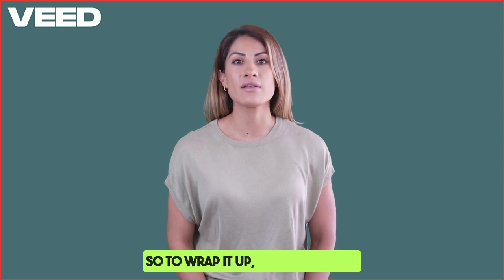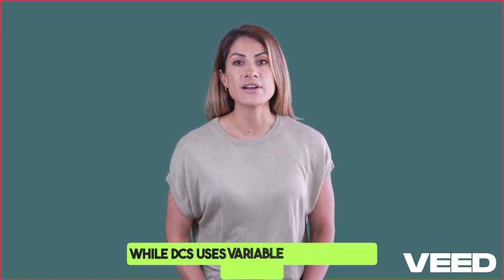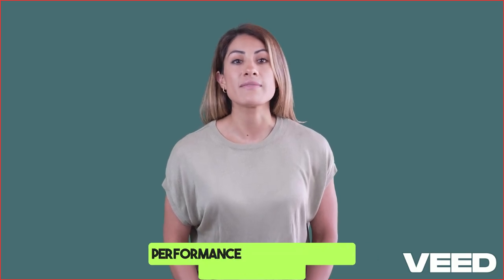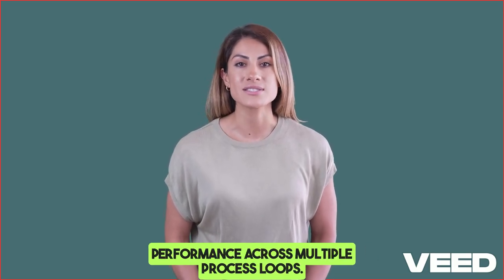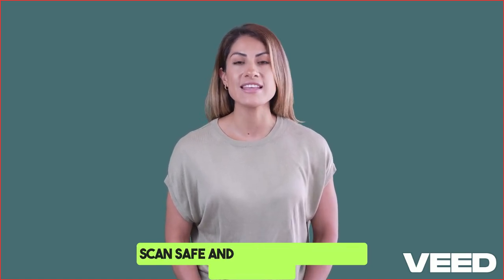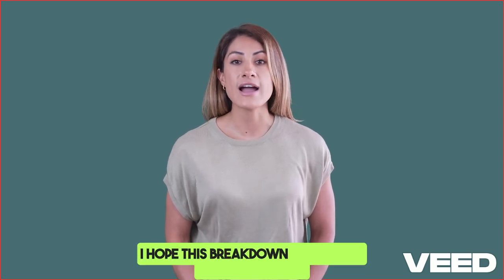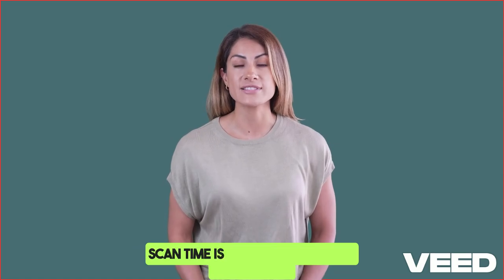So, to wrap it up, PLCs need fixed scan times for precision and high-speed control, while DCS uses variable scan times to optimize performance across multiple process loops. Both approaches are designed to ensure smooth, safe, and efficient industrial automation. I hope this breakdown helped you understand why scan time is a critical factor in automation.